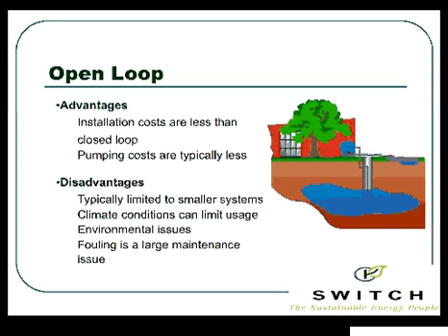Environmental issues, okay? How does the Cataraqui Regional Conservation Authority feel about you pumping water in and putting it through your heating and cooling system and dumping it out into a pond or into a creek, right? How does the Ministry of Fisheries feel? What do they think about that? Because you are changing the temperature of the water differently than Mother Nature, right? So that fish spawning bed might be affected. So those become environmental issues that you need to check on as that homeowner, as that potential system is being put in.